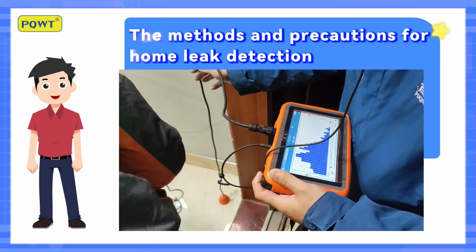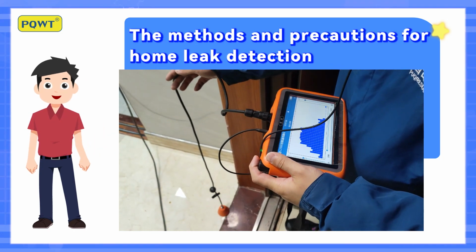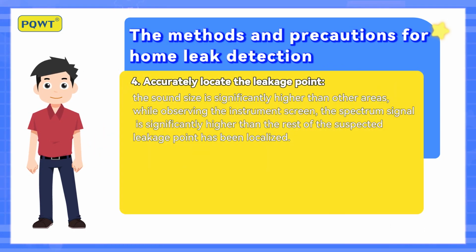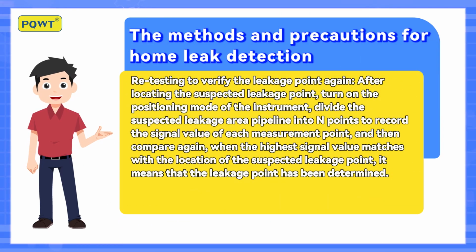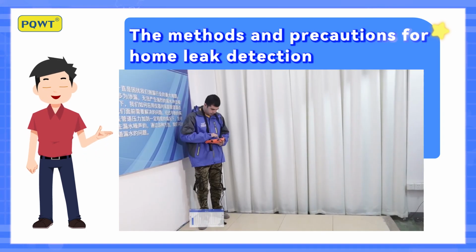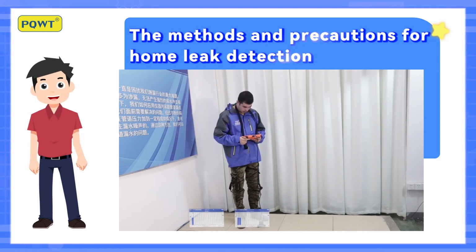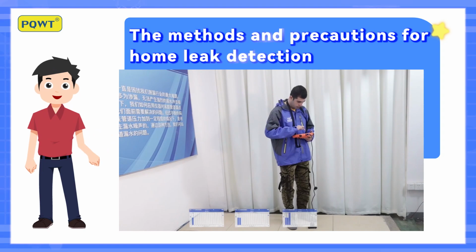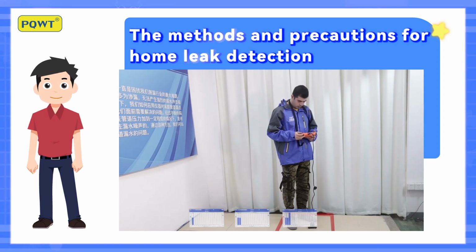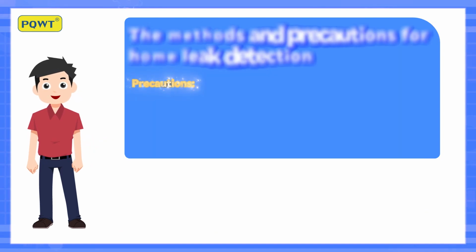While observing the instrument screen, if the spectrum signal is significantly higher than the rest, the suspected leakage point has been localized. Retest to verify the leakage point again. After locating the suspected leakage point, turn on the positioning mode of the instrument. Divide the suspected leakage area pipeline into endpoints, record the signal value of each measurement point, and then compare again. When the highest signal value matches the location of the suspected leakage point, it means that the leakage point has been determined.